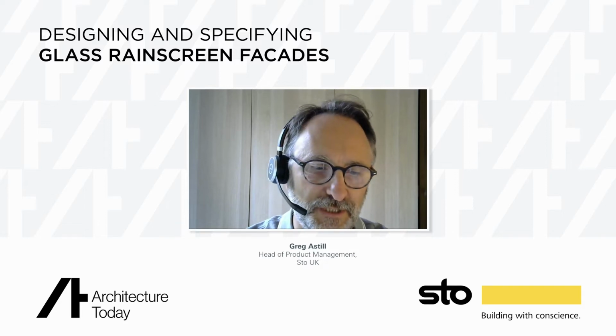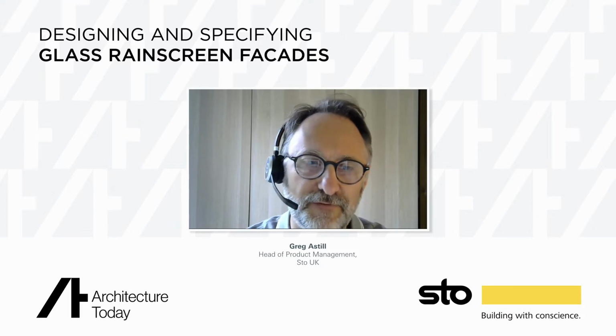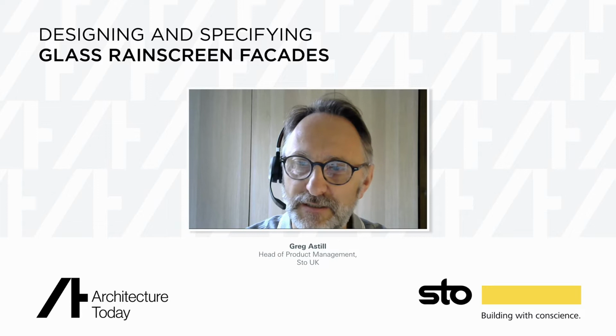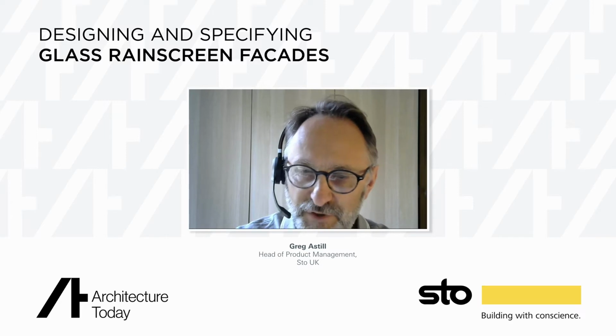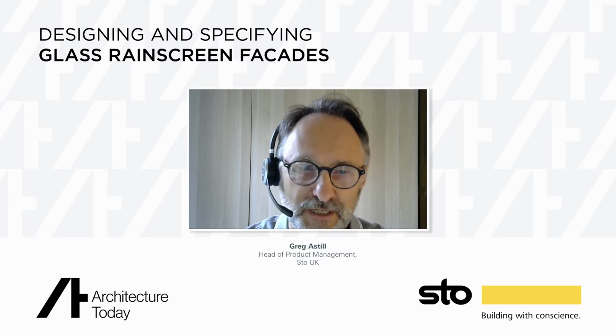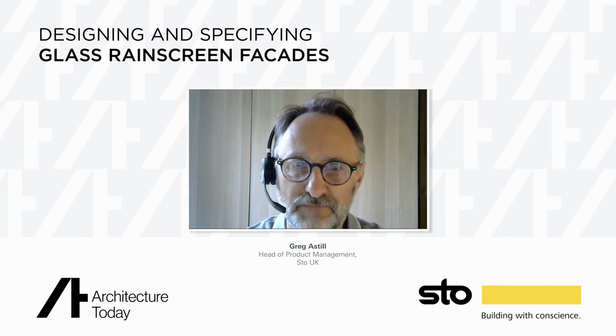When you go beyond a certain size, so typically above 2.6 by 1.25, then we use a thicker glass, an 8mm glass, to cope with, first of all, we have jointed panels behind to cope with the joints, and also for the larger format. So then you would increase the thickness by just 2mm. So really quite slim panels themselves.